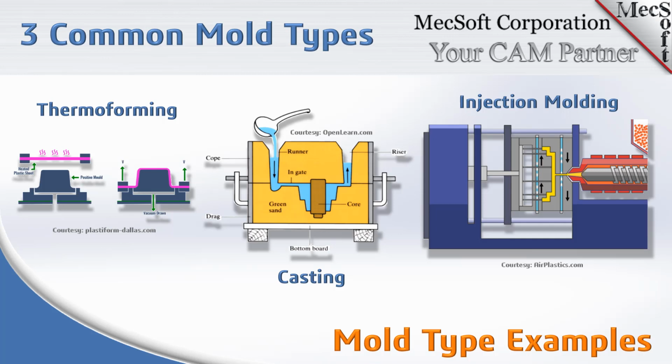So you have to create and machine that blank ahead of time, and then you use that to form each half of the mold. The material is like a green sand that sticks together, and it creates a cavity from that blank.